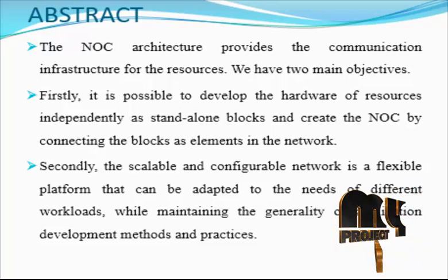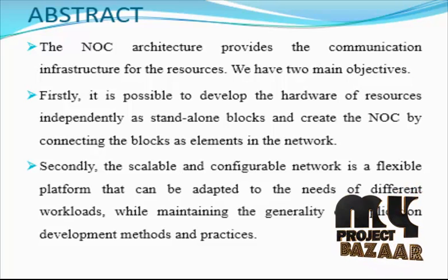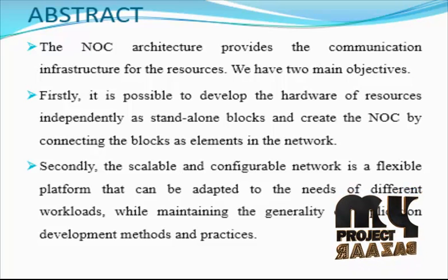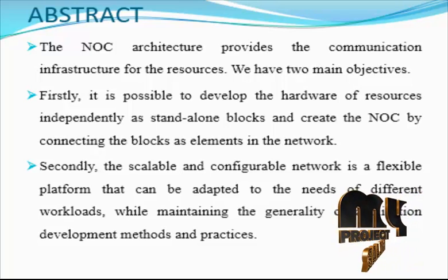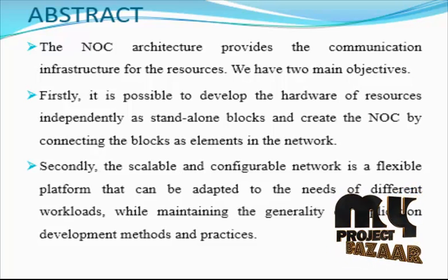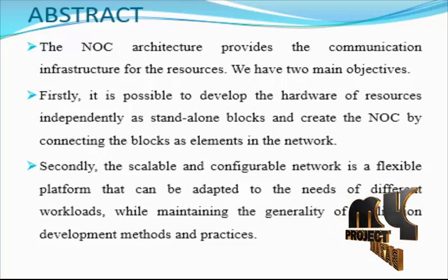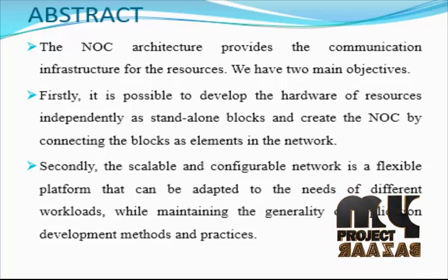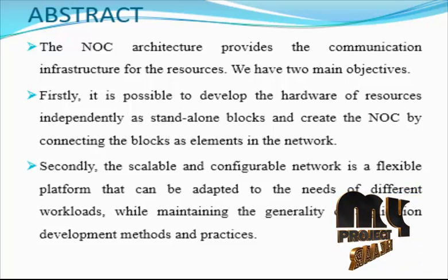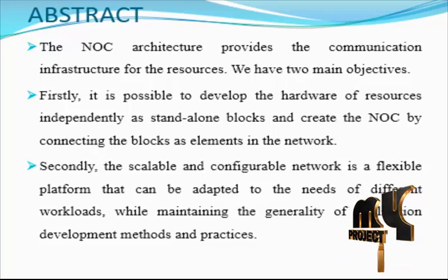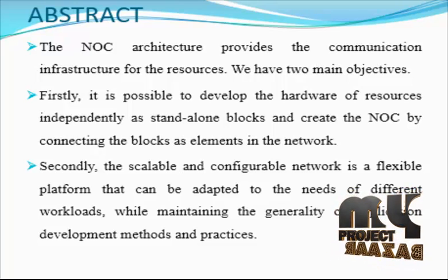Network on chip is an increasingly popular communication infrastructure in single chip VLSI designs for enhancing parallelism and system scalability. Processing elements connect to the connection topology via NOC switches, which are responsible for runtime establishment and management of inter-processing element communication channels. Since NOC switch design directly affects overall system performance and the exploited communication parallelism, much previous work focused on efficient NOC switch design.